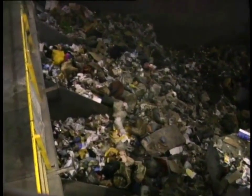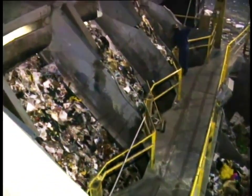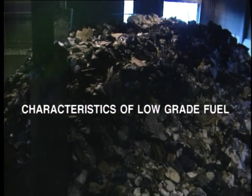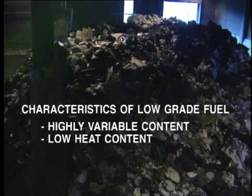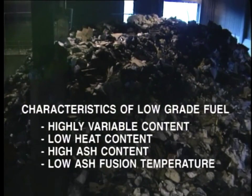In this segment, we'll take a look at combustion equipment used to burn low-grade fuels. A low-grade fuel usually contains one or more of the following undesirable characteristics: highly variable content, municipal waste, for example; low heat content; high ash content; low ash fusion temperature.